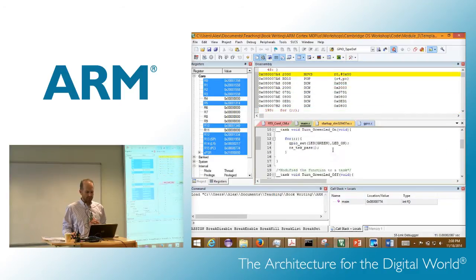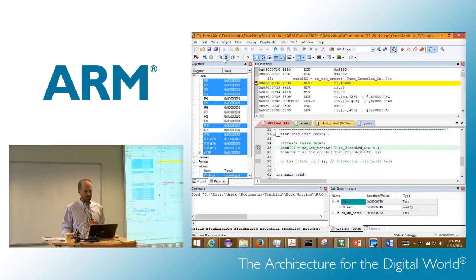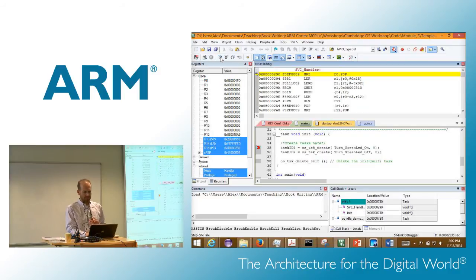When you single step through the code here, for example, you're going to need to set a breakpoint before entering the task create, and then you're going to single step into that. You're going to want to select the disassembly window and then step through this code. You can also do it with F11, the accelerator key. And up here in brown, you can see a label, service handler. So that's the actual name of the function that the disassembler is showing you.